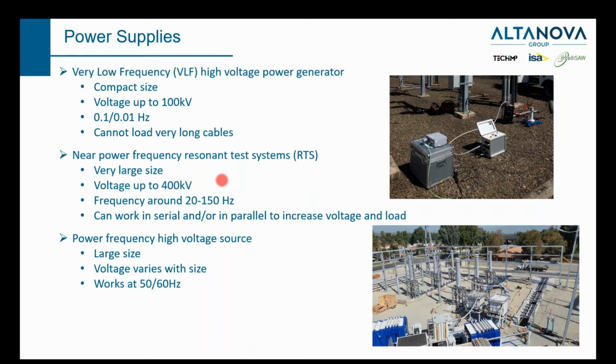So that's an LC resonance circuit with different resonance frequencies. The voltage can be pretty high, and the size of the resonance power supply is also large. Here's an example. It requires the signal generator, inductor, and the big insulator to support the testing lead to do the test.